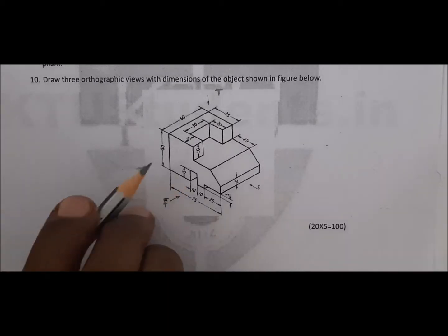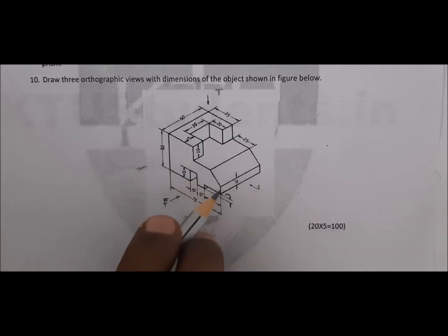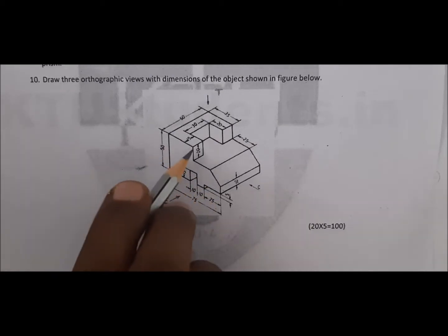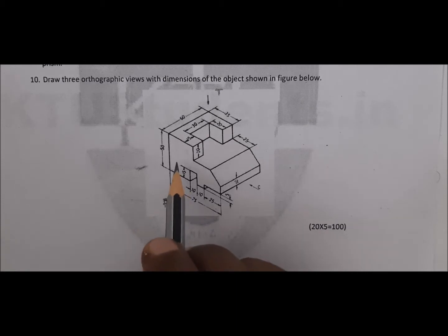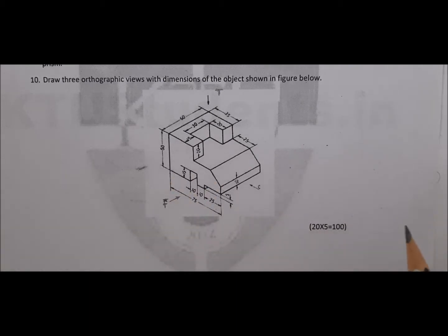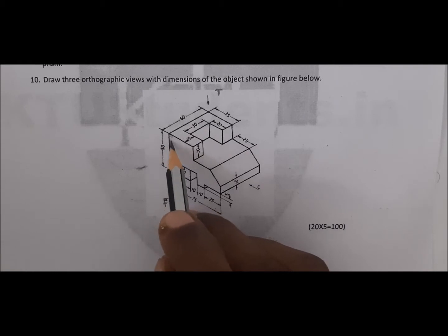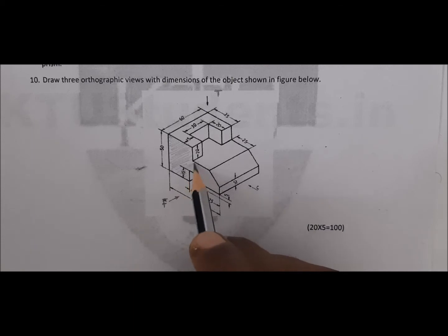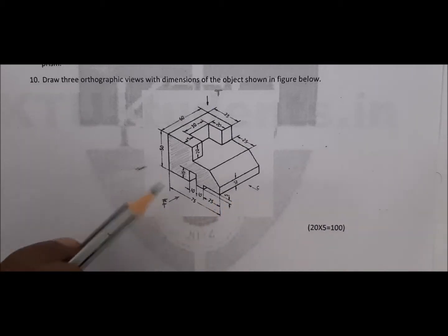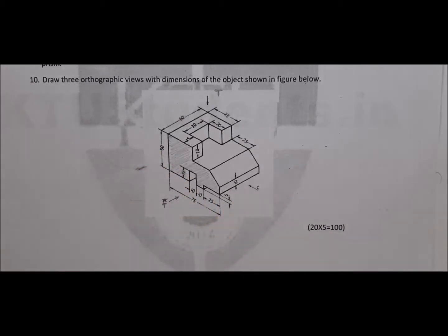So when you look from here, what do you see in the 2D figure? You see the 2D outline of this figure. Okay, so the best way to tackle this is, imagine that if you are lighting a torch from here, on which all surfaces the light will fall. Okay, I'm going to shade that surface. So this is a surface where the light falls. There is a cavity here, right? So if it is exactly perpendicular in this direction, the light will only fall on this shaded surface. So that's exactly what you need to draw.